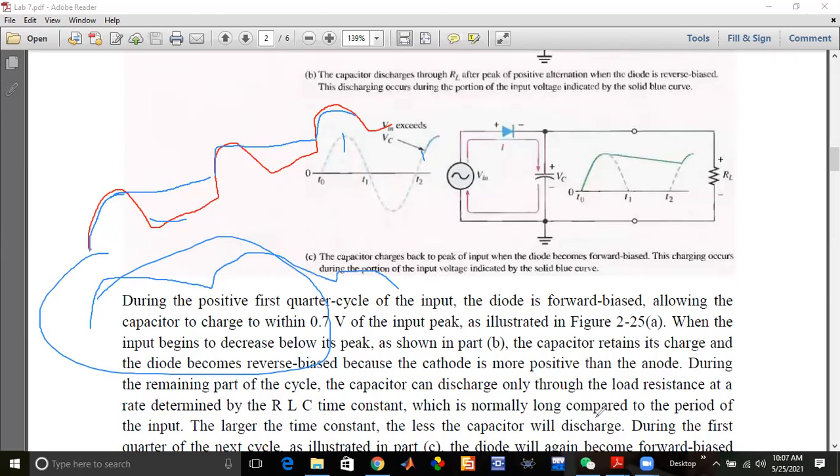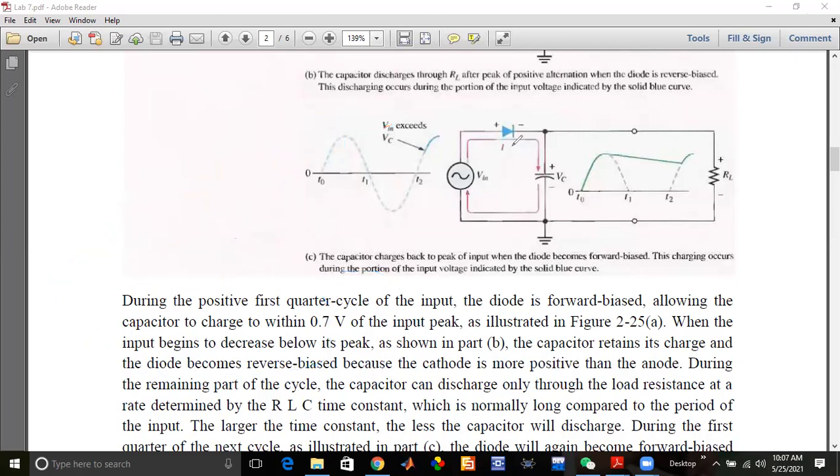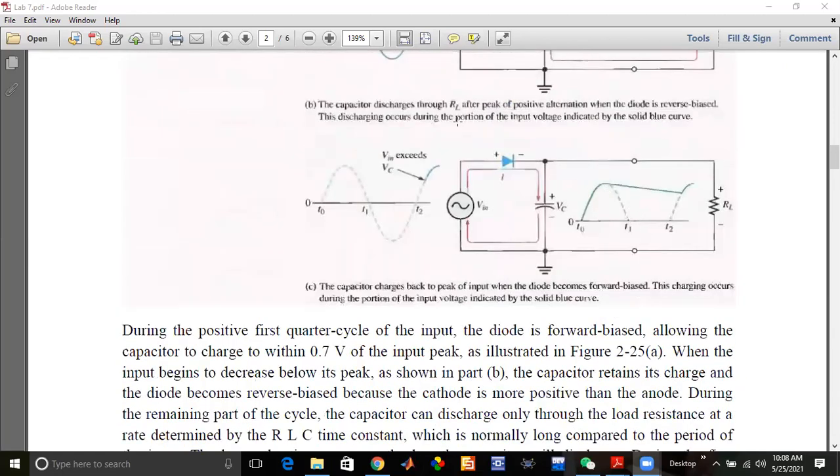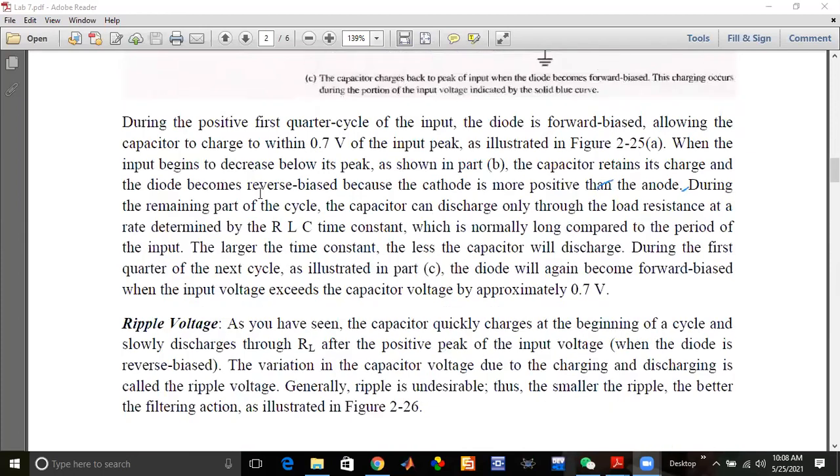It means by applying the capacitor, the output of the half wave rectifier will be filtered and the fluctuation will be reduced. When we apply the regulator IC, the fluctuation will become even smaller. Now the variation from this peak to this peak is called peak to peak variation, and it is denoted by a factor which is called ripple factor.